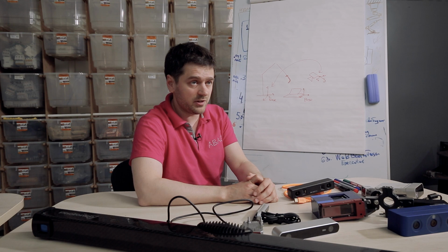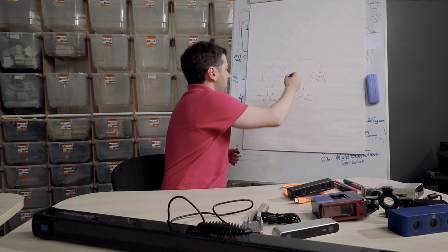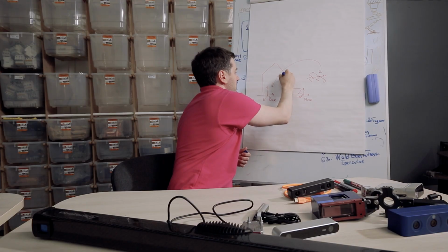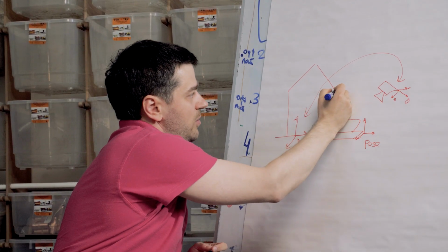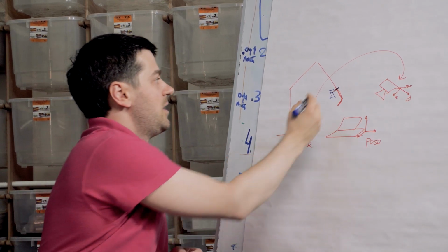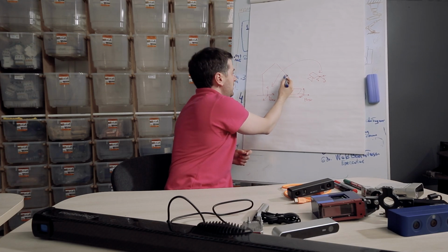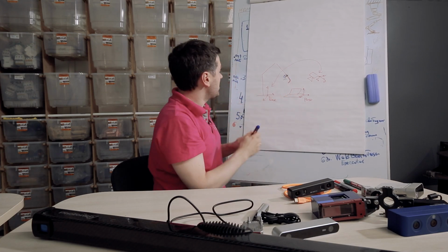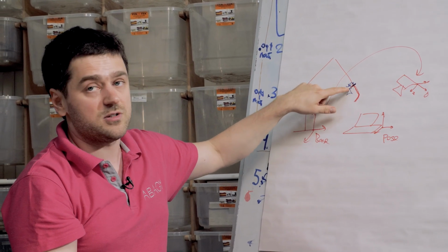In industrial robotics, for robot arms, there is a special kind of extrinsic calibration called hand-eye calibration. For example, if we have our robot and the camera installed on it, we know in every moment of time the position of the flange of the robot, but we don't know the transformation between the flange of the robot and our camera. And there is a special procedure how to get this transformation.